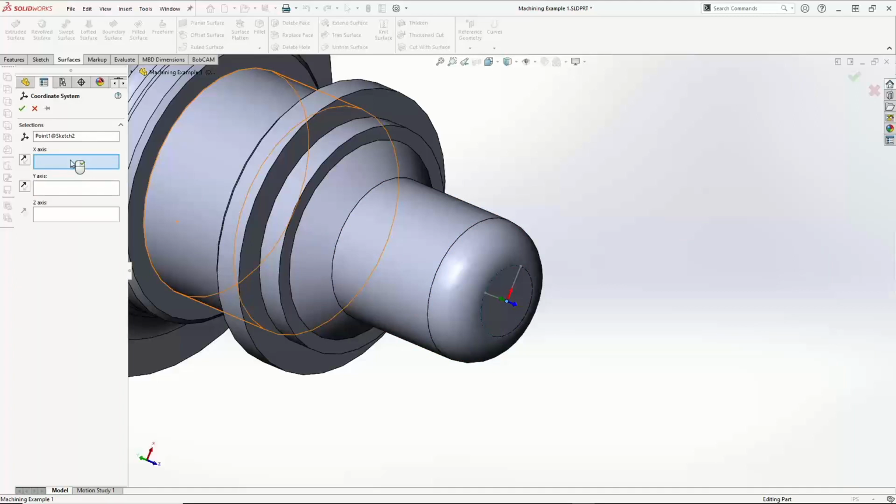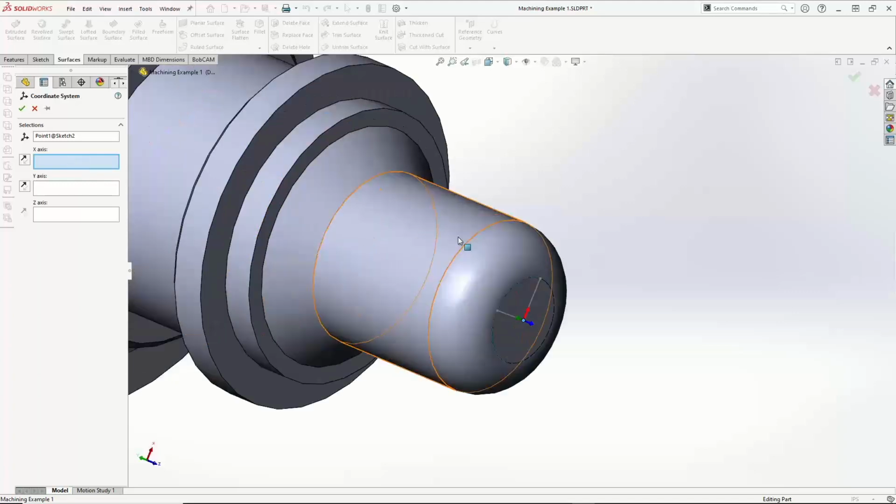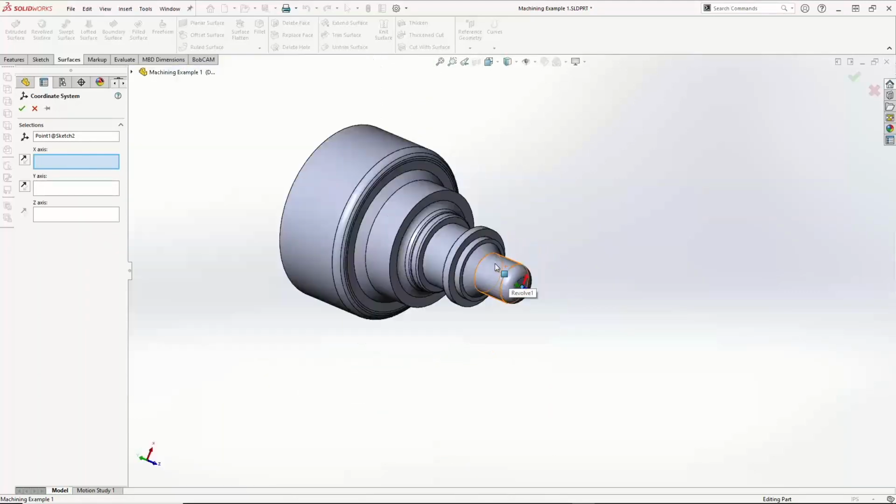And then I have to go and define my X and Y axis. Now, Brock, if you're using the standalone version, you won't have to do this. You'll just make sure your part is laid down on the left side of the crosshairs. So you want the front face of your part right at XYZ0, and you want it centered on XYZ0. Because really, when we define turning, we're only looking at half the part. Whatever you pick on one side is going to get revolved and cut the same way.